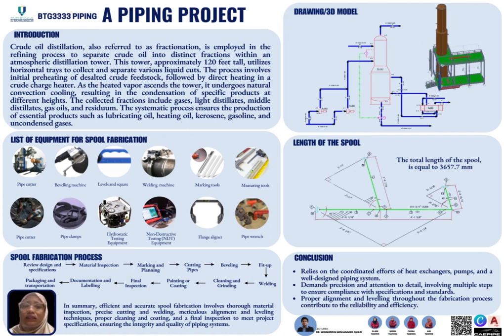And sixth, assembling pipes, fittings, and flanges according to the drawings is our fit-up step. Tack welds may be used to hold everything in place. Now the magic happens: we weld the joints, using different techniques. Make sure to follow the procedure. Non-destructive examination ensures weld integrity.